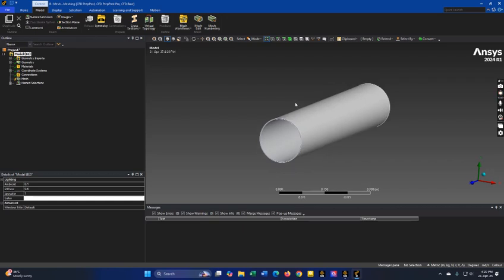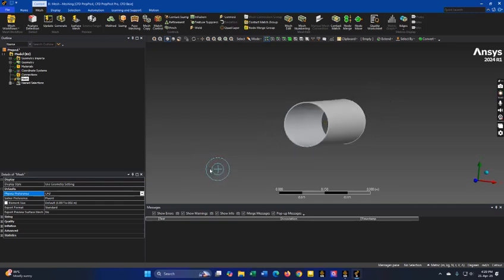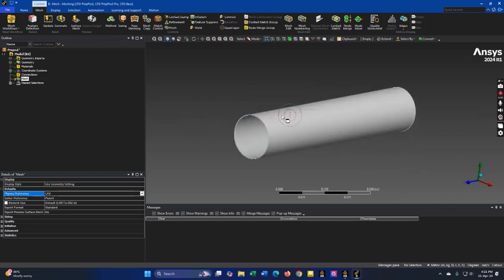Before going any further, select the mesh first and change it to CFD, as this is a CFD experiment, not a mechanical experiment. Next I will be giving it a global meshing. Global meshing means you select a shape that will be applied for the whole body.